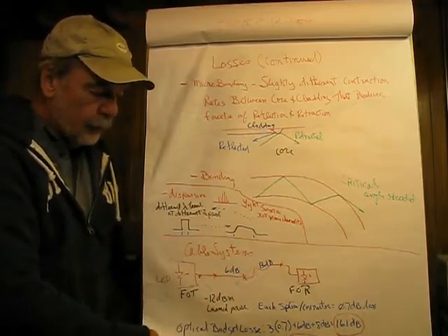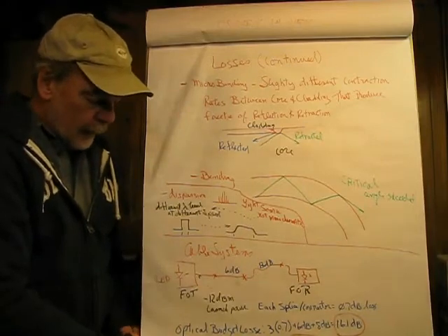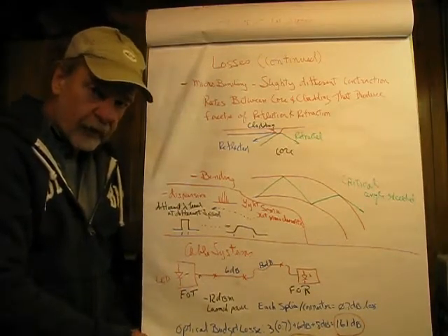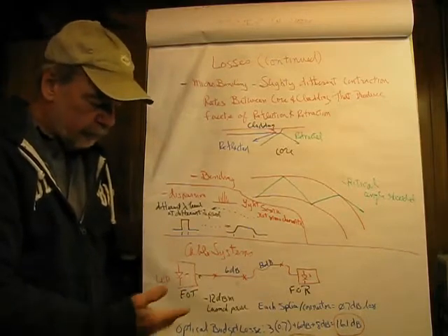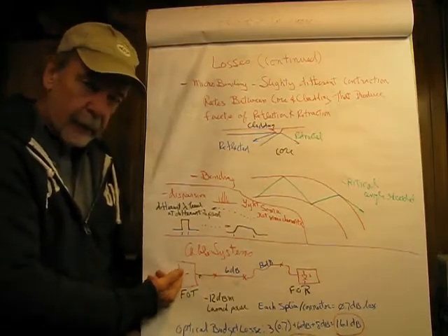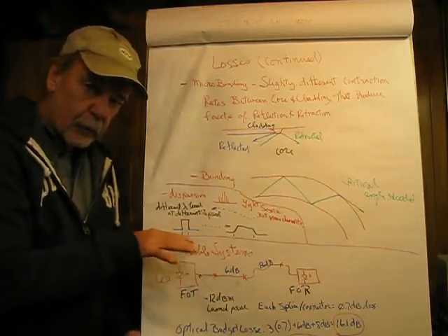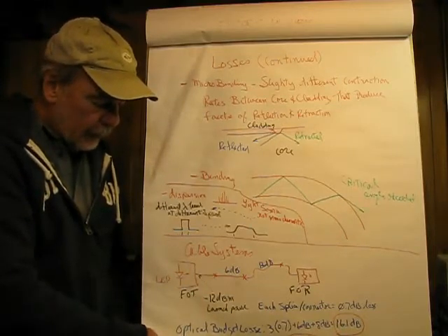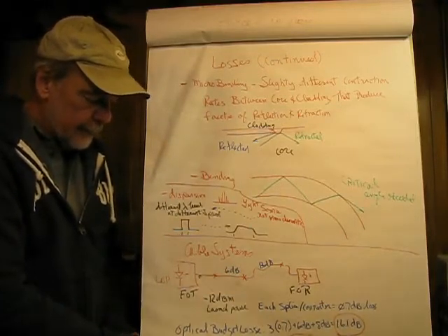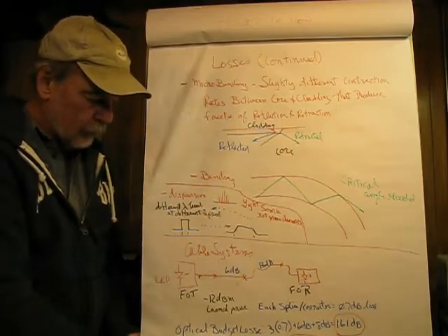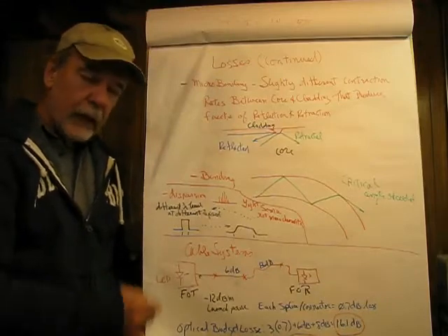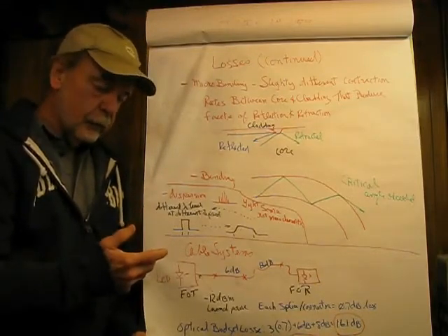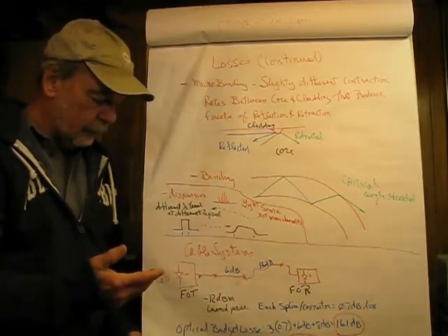So always have to know what your receiver needs. Have to know what your transmitter's transmitting. If this is wearing out, and they do, because changes happen, these run hot, things tend to move around a little bit. So if the output power drops significantly, it would cause an increased loss of the overall system. It can drop out of range of the receiver, which means, of course, a lot of receiver errors.